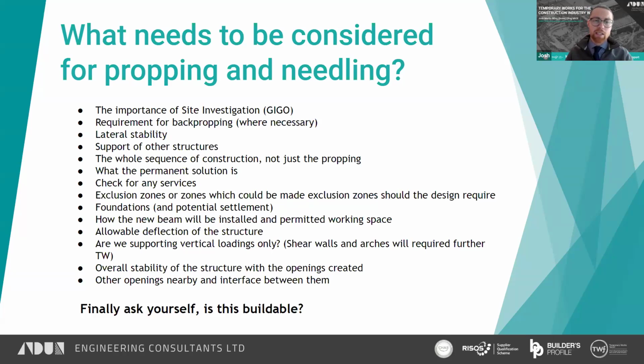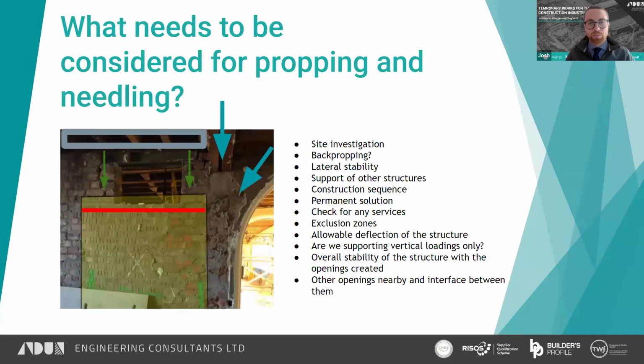And then finally, you need to ask yourself, is this solution buildable? It's really important that the design, from both the permanent works and the temporary works, is buildable and suitably mitigates risk using the ERIC principle of eliminate, reduce, inform, and control. That hierarchical control of risk. Openings in load-bearing walls and structures can go seriously wrong if not carried out correctly. So the overall solution must be safe and the sequence of construction must be practical and buildable.